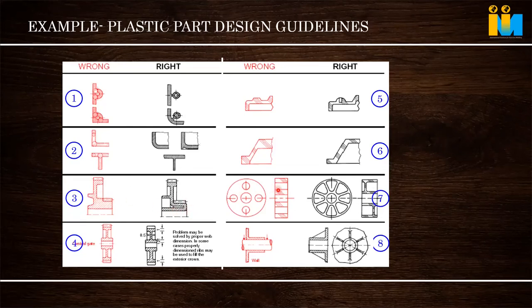So here we can see, I want this type of holes. Here I am not able to maintain uniform wall thickness. With this construction design change, uniform wall thickness is also maintained. At the same time, these holes are given for reducing the weight of the part. It has been redesigned in this manner so that it reduces the weight and gives uniform wall thickness, better filling, easy molding, everything is possible.